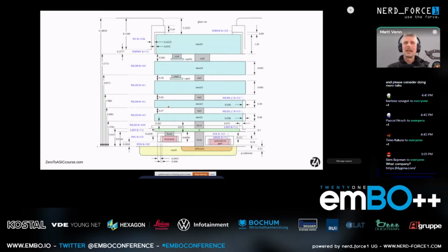So here's a cross-section of the PDK that we have access to. And this bottom part here is where we build the transistors. And then we're using metal 1 for interconnects within the design. And then metal 2, 3, 4, and 5 to kind of make connections outside of that design. So it's a bit like having a 4-layer circuit board and millions of MOSFETs all in one package. So you can kind of see the power of that, but also how quickly things get really huge and unmanageable.